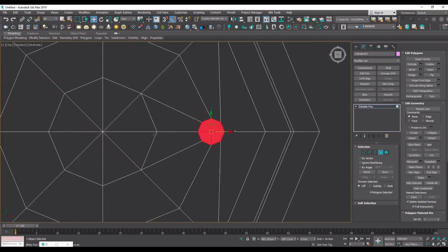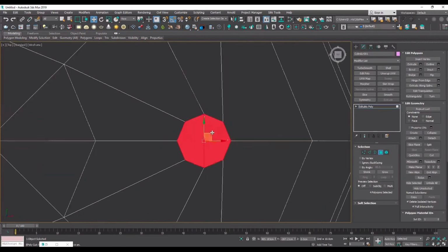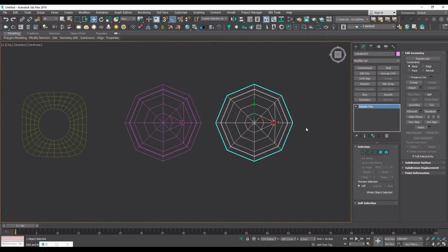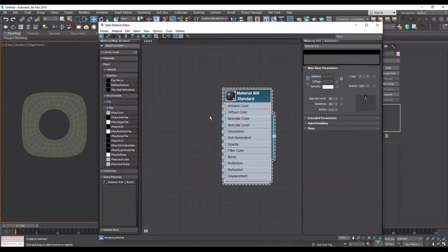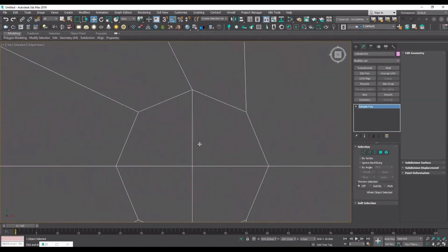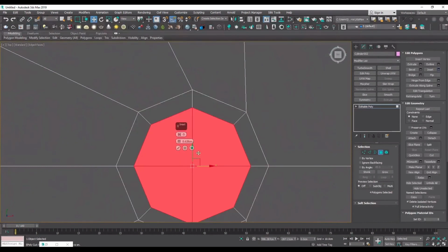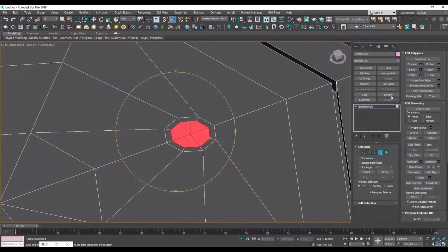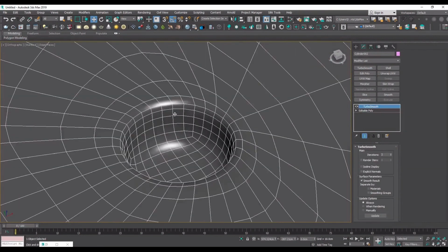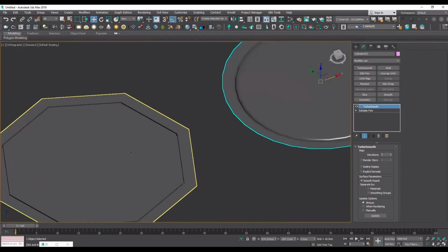I will take a copy now from our model and add the hard surface material to it. But first, let us continue with the correct model and the one with the extra inset. So I add an inset inside and then I extrude downwards. Now, I give it the turbo smooth command, and very well. You see, it is in fact clear and good.